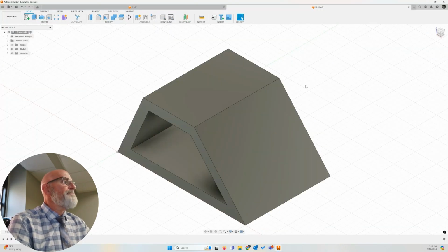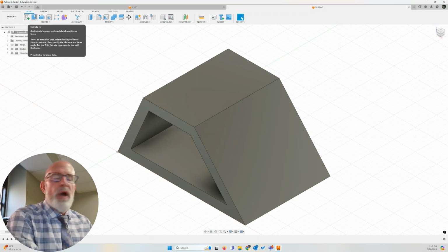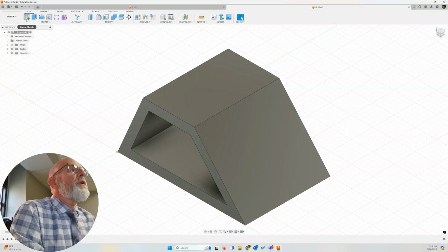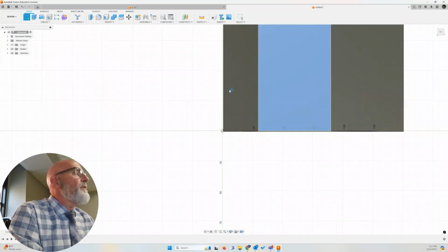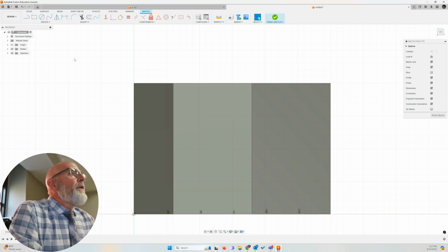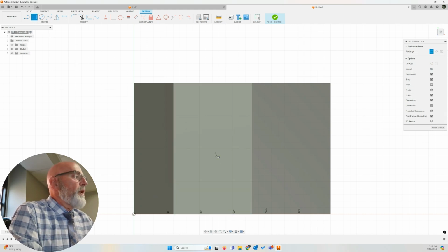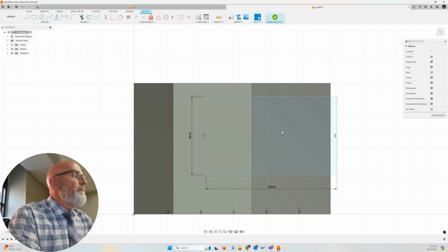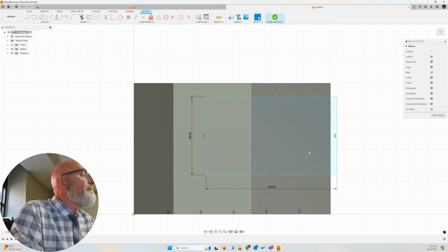Let's go do that. We're going to create sketch. Now, once again, I want to access the geometry of this shape. So we're going to create our sketch on this face. There we are. Let's create our rectangle, 2-point rectangle. And I'm going to do a better job this time so that it moves around. So we're going to go 100 millimeters this direction, and it's going to be 60 millimeters that direction. So there we are.